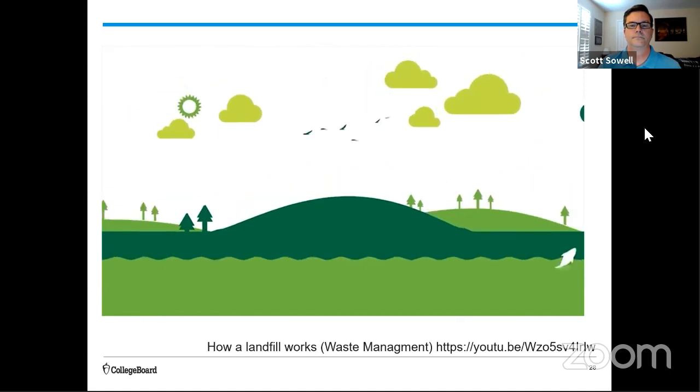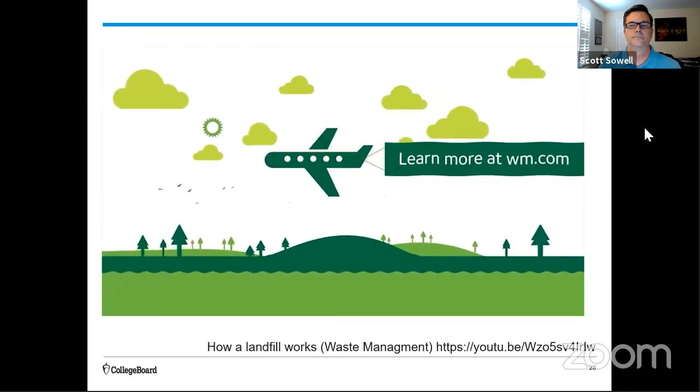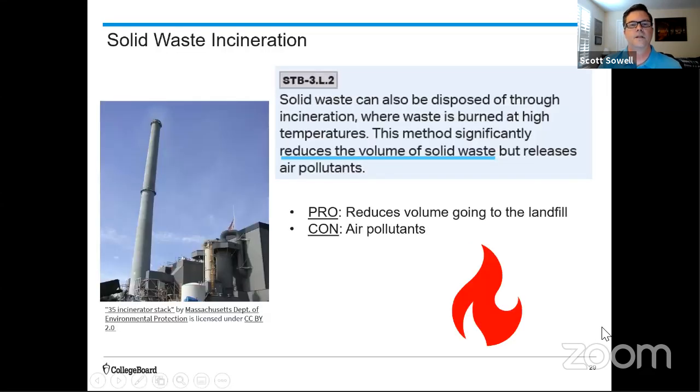So, the volume of solid waste in a landfill is an issue. The more solid waste in the landfill, the more methane that's going to be generated, the more leachate that's going to be generated. And those two things we have to deal with. So anything that we can do to reduce the volume of solid waste in the landfill is something we should explore. And one of those ways, which is pretty common, is incineration.